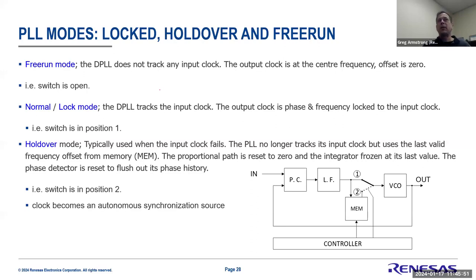And the other advantage that PLLs give you is there are other modes of operation that you don't commonly get if you're just looking at a very simplistic clock circuit. And the main one is the concept of holdover, which we'll get into as well. But the idea of holdover is it's almost like a memory of saying, I'm going to try to remember on average where my offset is of the local clock to the primary clock, so that if I lose that reference,